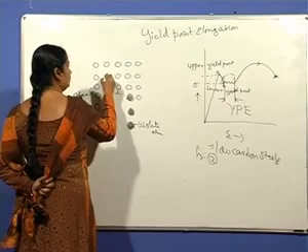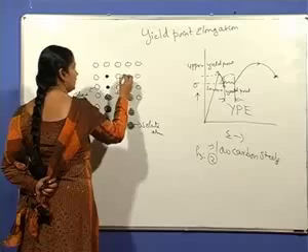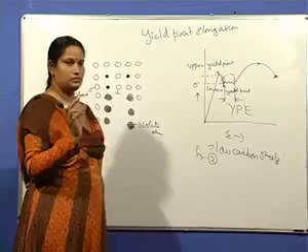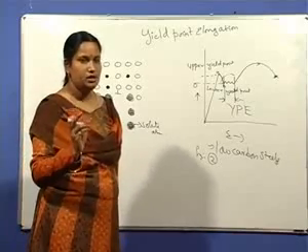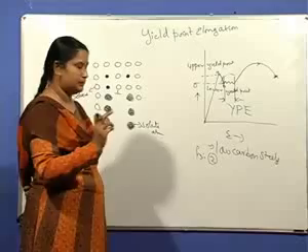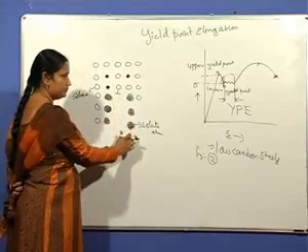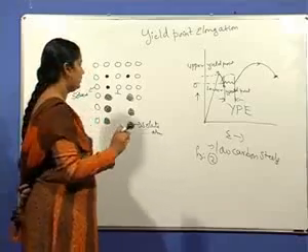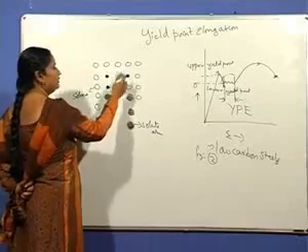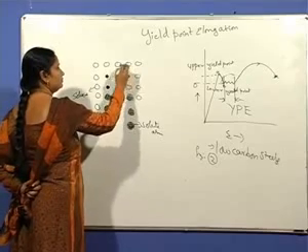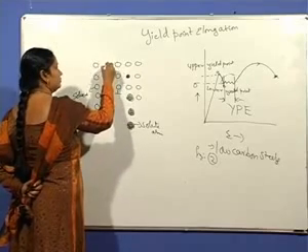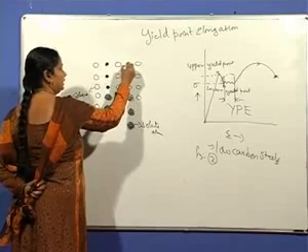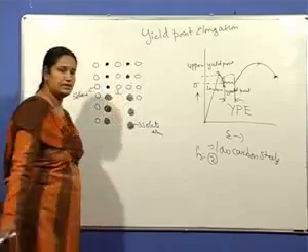I'm representing both in the same figure. So please try to understand that if the solute atom is slightly greater than the solvent atom, they occupy the positions below the edge dislocation. If the solute atom is slightly smaller than the solvent atom, they occupy the position above the edge dislocation. So two figures, I am combining it. I am not drawing a separate one for both the cases. Both the cases are superimposed in the same one.